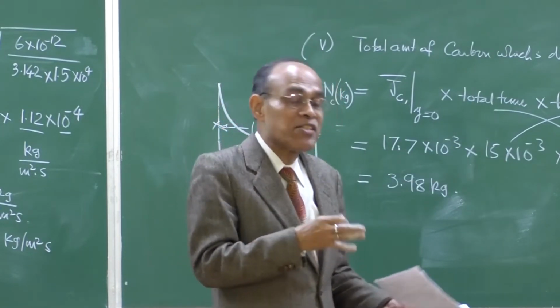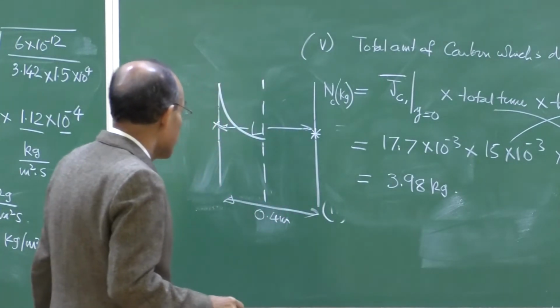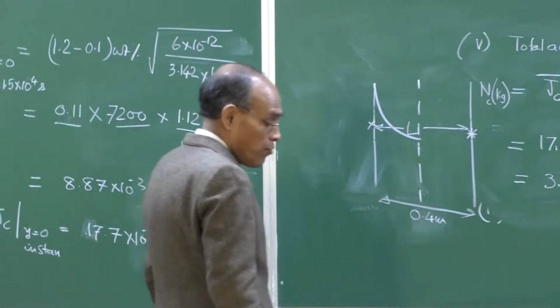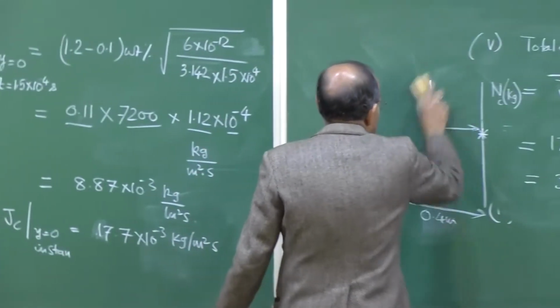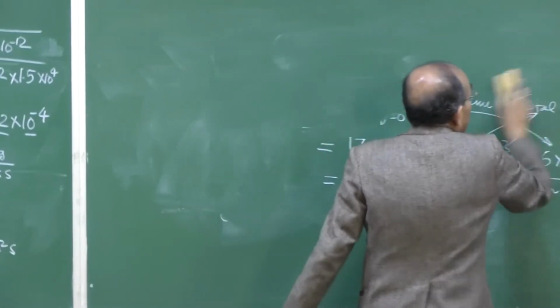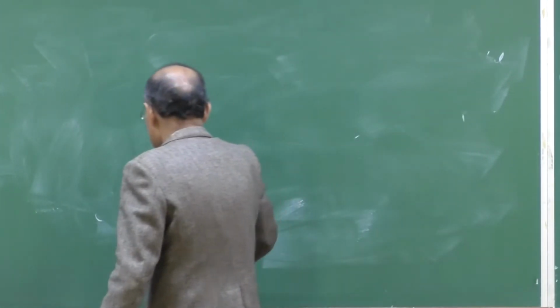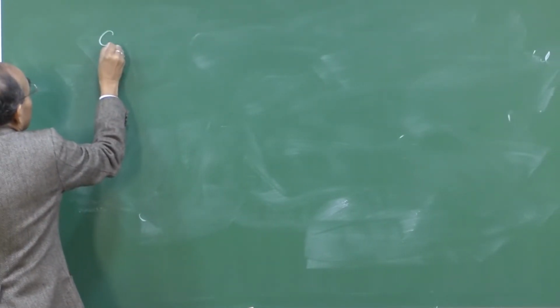In one case it may be 900, the other case it may be 1200 or 1300 degrees centigrade. So, you may be asked to compute the relative rate of penetration corresponding to 2 different temperatures. In that context, suppose I pose the problem as carbon diffusing in steel,